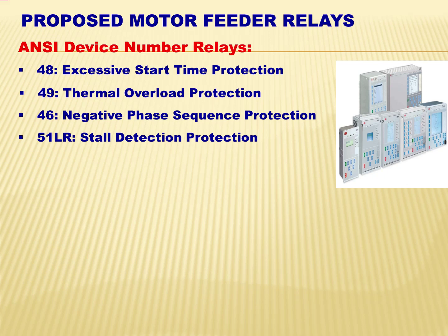If the motor fails to run up to full speed during the starting period or is suddenly forced to run at a low or zero speed, then the stator current will be at or near its starting value. This will cause overheating of the stator and rotor conductors, and the lack of cooling airflow will aggravate the problem.